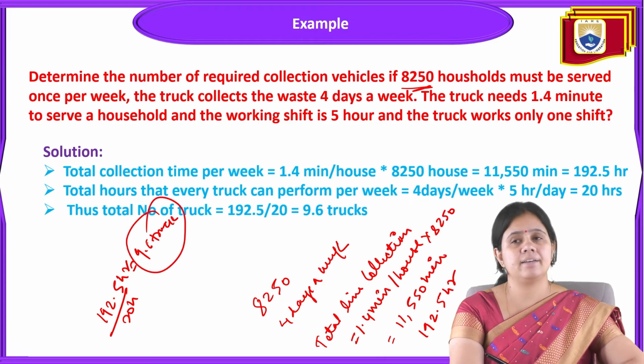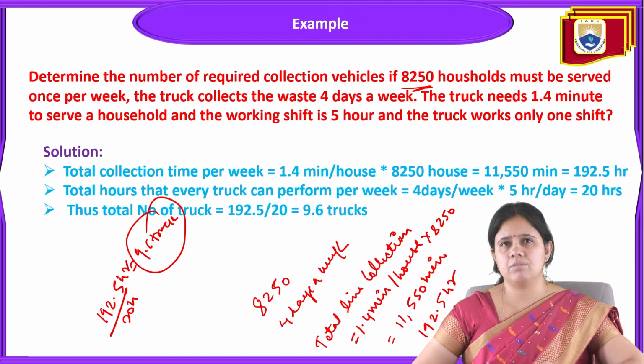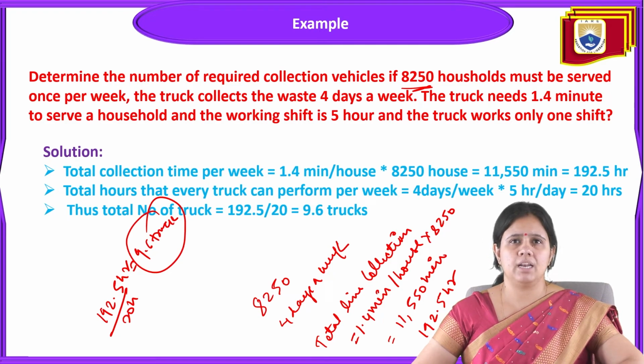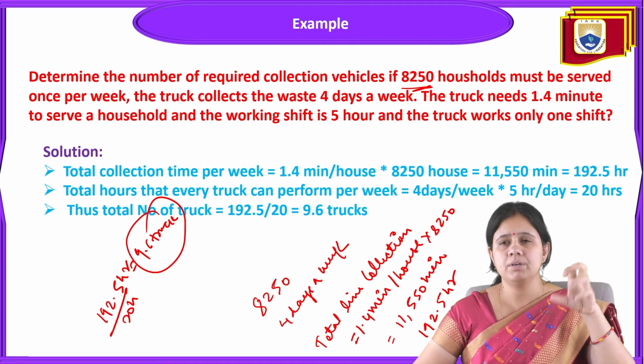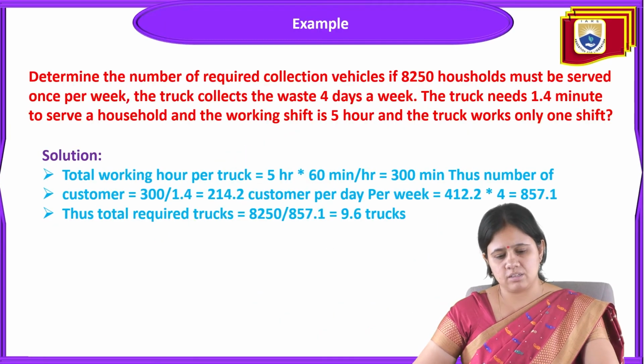Then approximately it needs 9 or 10 trucks. So if there are 8,250 households, and the truck collects waste 4 days a week, and the truck needs 1.4 minutes to serve a household, and the working shift is 5 hours, and the truck works only one shift, then it needs 9.6 trucks to collect all the waste from these households. So this numerical is to calculate how many trucks are required to collect this much solid waste. And for this question, another solution is there.